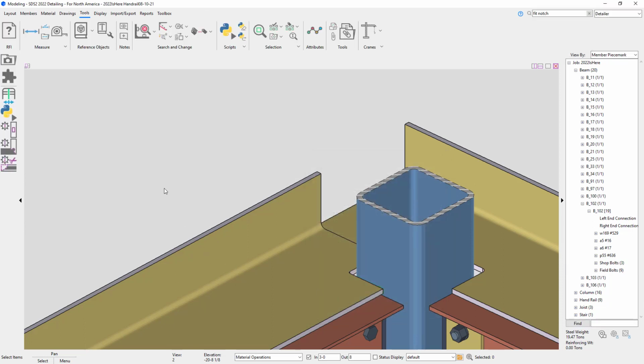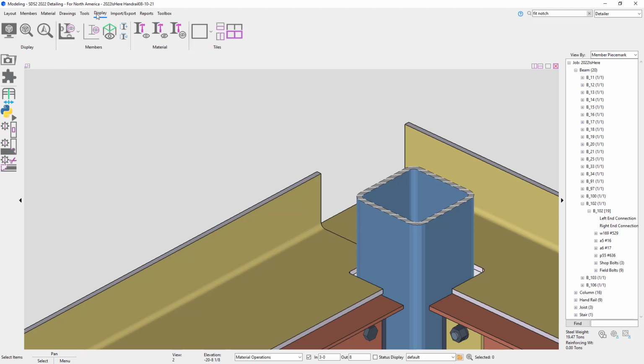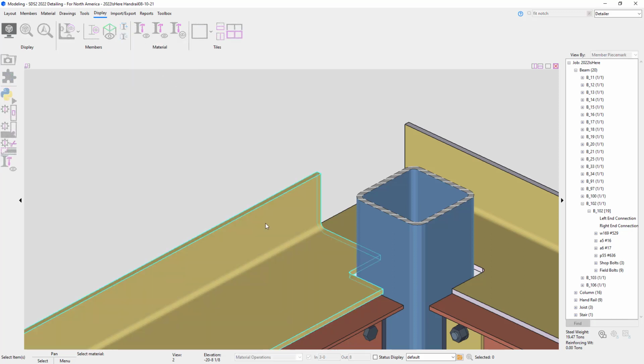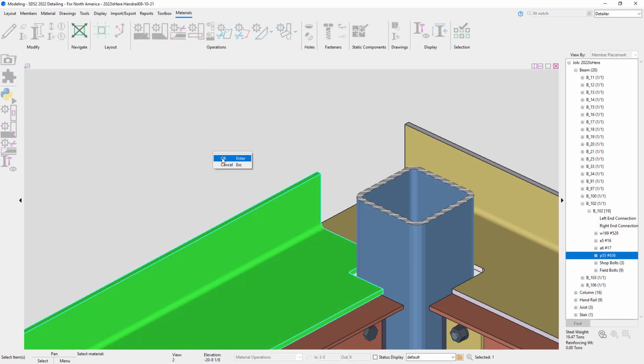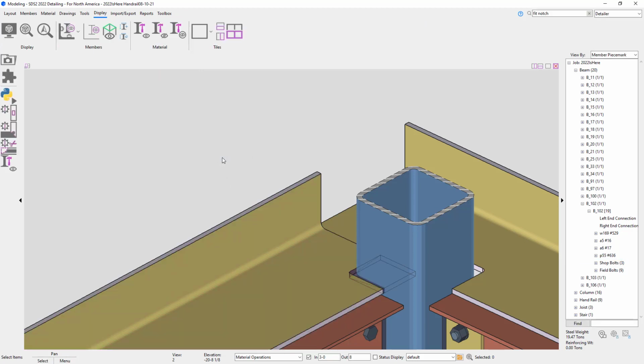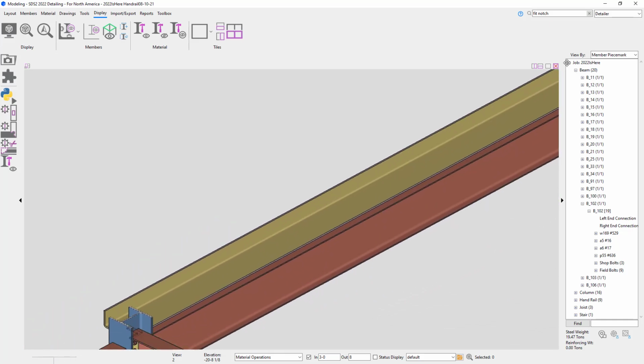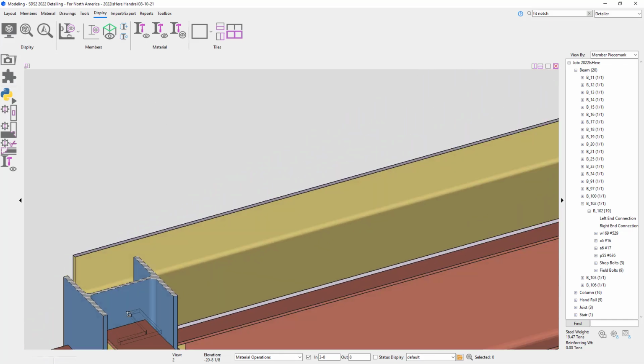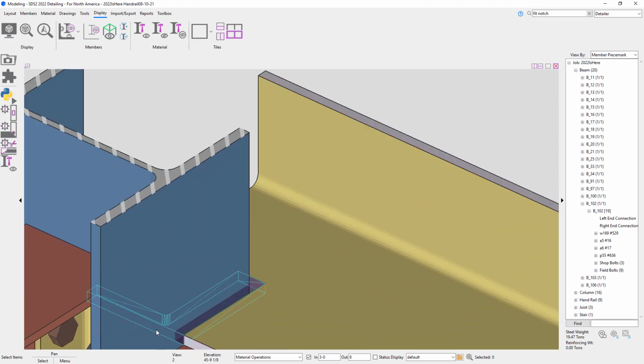In my display, there are 3 options under my material. There's show material fit operations. So I would click on the material so you can see the material fit operation. And since I have material operations selected in my selection filter, I can just go ahead and double click on that and edit the material fit operation. So maybe I'll just change this to a 1/4 inch.